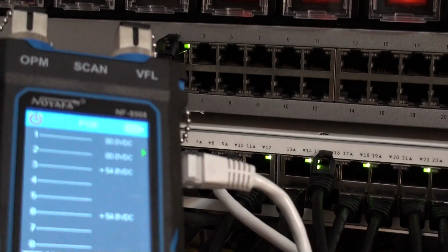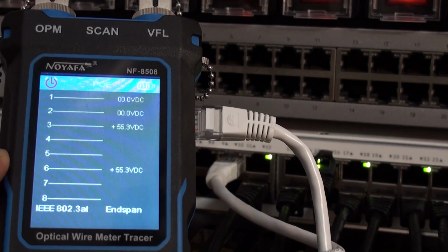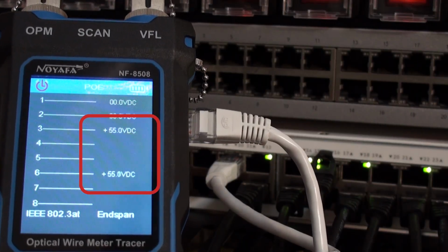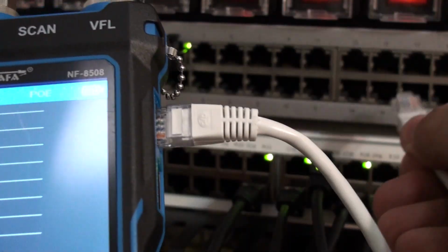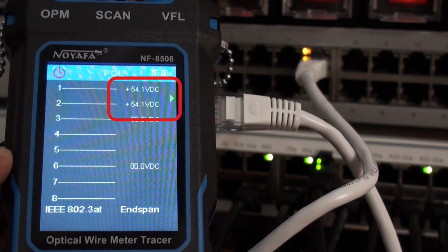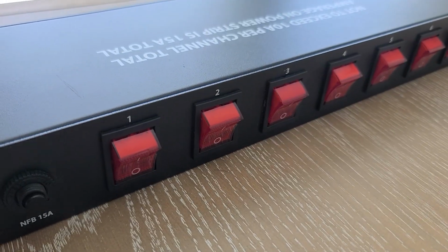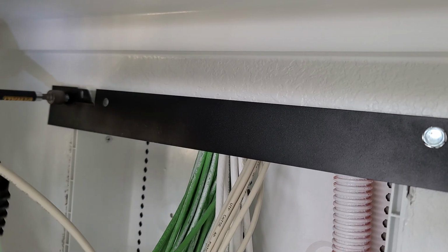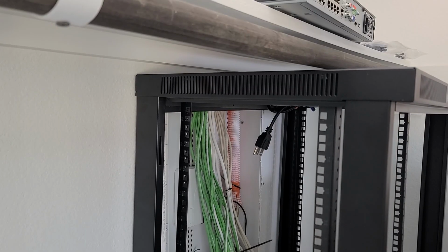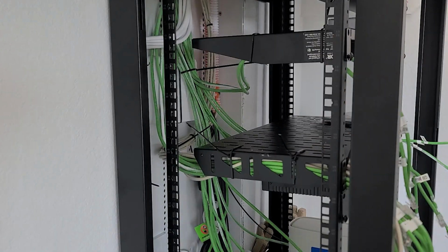We can also use devices like this, not only to diagnose if our cable has been properly terminated, but also to be able to verify if the port to which we are connecting provides electricity, what is the voltage that it is providing, but most importantly, if it is a standard PoE or not. We'll leave you the links in the description if you want to be the ones who install absolutely everything, and in that case, these devices would be very practical to have in your toolbox.